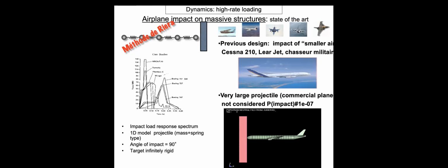And then basically the plane would hit the obstacle. It could be the protection structure of a nuclear power plant, or the other structure trying to protect. And then without modeling what happens with the obstacle, you would assume that the plane is an elastoplastic bar. So by hitting the obstacle, the elastoplastic bar would plastify. You have dissipation. And then you take the kinetic energy minus the dissipation, and you have the remaining energy which has to be taken by this obstacle, and you spread it over a certain time. Then you have this kind of response spectrum analysis stuff, how you can design and how this could be handled.